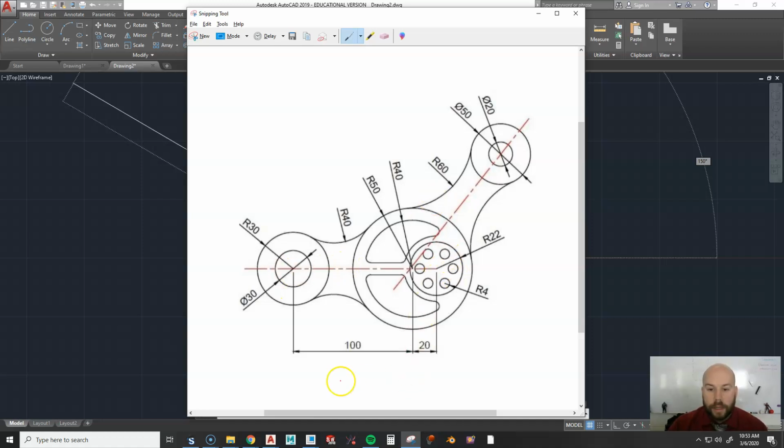The other thing is we can assume, again, that maybe this same circle is also 100 away, but there's no dimension saying that. Okay, and we could have avoided that very easily by just going 2 times. So already this instructor is setting up their, I don't know how you grade somebody when you don't give them enough information to actually create something. The other thing that I did notice as well, which we'll get to, there's no dimension for the diameter that these circles are on. Okay, I can figure out the angles because they look equally spaced, but there's nothing indicating that there are. There's nothing even indicating that these are all the same size.